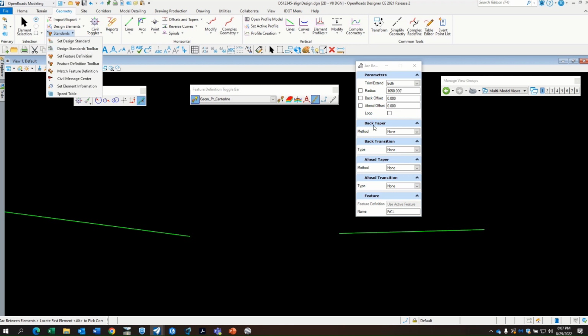I could actually do that, and if that was set and I had set the 50 mile per hour design speed and all that, when I go to create a fillet, it would actually set that radius to the 50 mile per hour radius, which you could choose to use or not to use, or go with something flatter, which is what I did in this case.